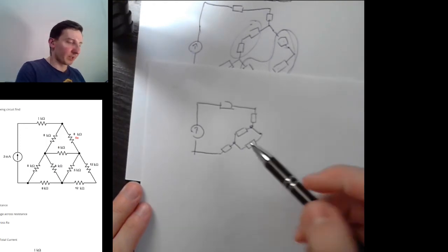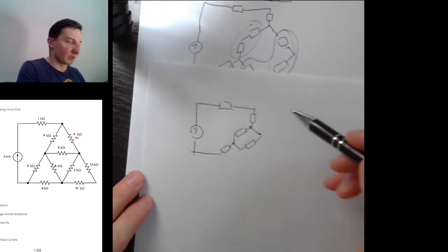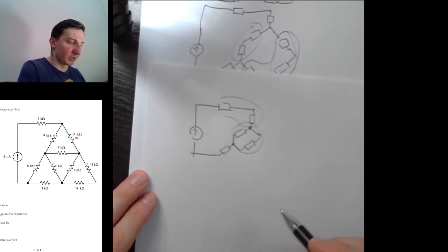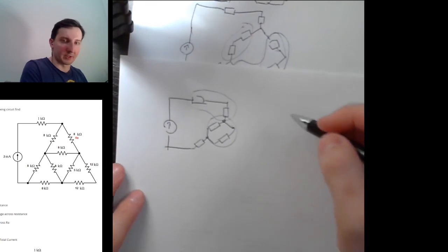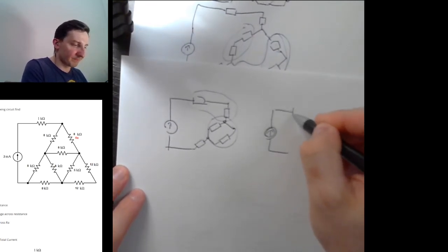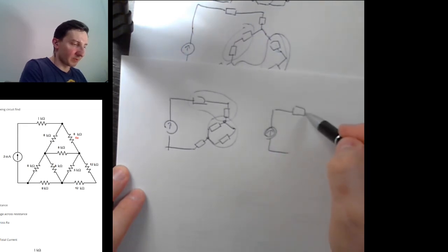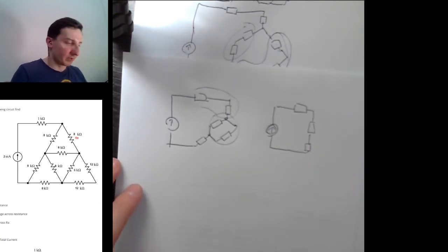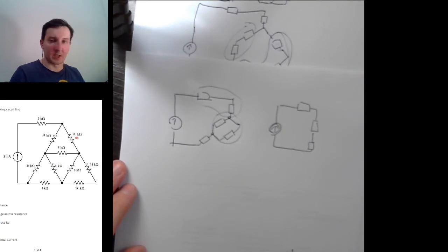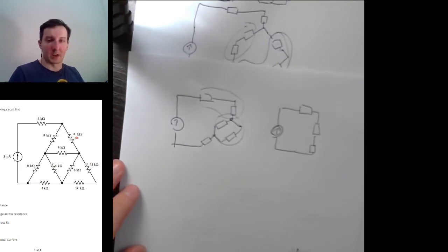Having this, we have resistors in series right here, in parallel in here, which can be simplified to something like this: a single resistor, a single one, and the last. Okay, so we end up with a really easy scheme with 3 resistors in series, and we can easily calculate the equivalent resistance by adding these resistances.